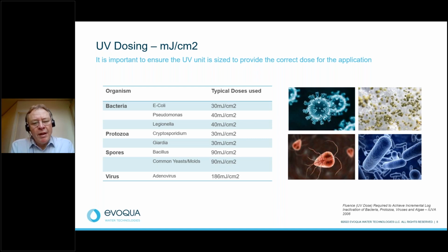And also chemicals. So for example, dechlorination. These have much higher doses. You might see doses of anything between 700 and 1,000 for a dechlorination application. Deozonation typically would be around 100 or just over 100 dose as well. So again, chemical treatments, breakdown of chemicals, generally requiring much more power and dose.